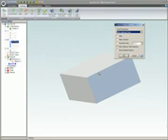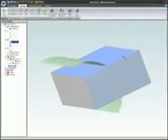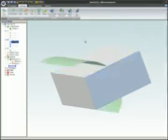In the Insert Surface Options dialog, Face Processing is set to None, since this is the only surface being imported. The first three options can be left unchecked for the same reason. When the OK button is clicked, the surface appears intersecting the rectangular part.